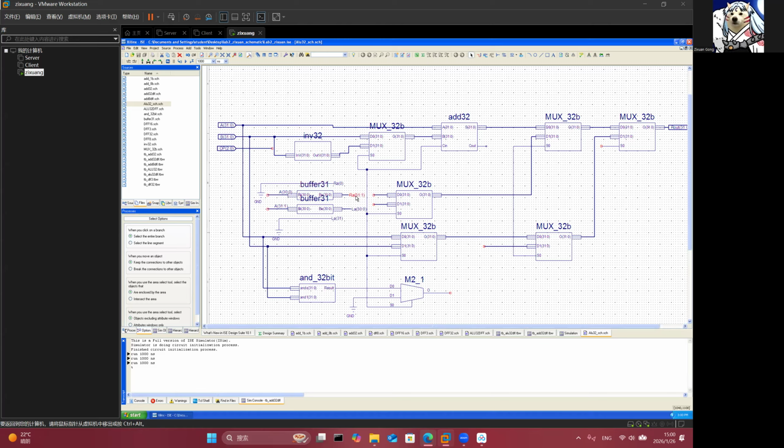As a result, the wires will be 1 to 31, and the LSB will be 0. So I connect the LSB with ground. In the same way, if we want to shift left 1 bit, we could use the highest bits from 1 to 31 to 0, 30.